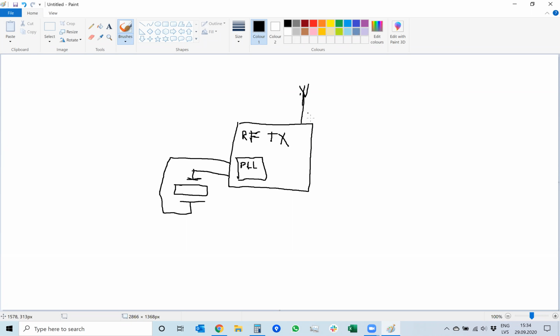So we can buy a crystal that is an electromechanical component, which when bent generates a small voltage, and you can use it to bend it to the opposite side, and then it produces the opposite voltage, and basically you can make an oscillator out of this quartz crystal.